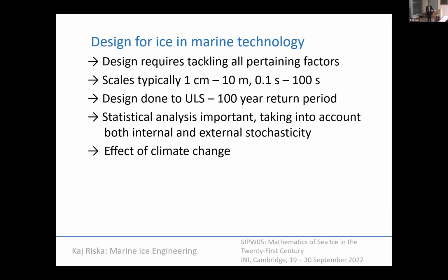Then there's an effect of climate change. That has been debated a lot. And actually the present opinion in engineering is that if your statistics proves that there is some sort of effect of making the conditions more benign, less severe, what you should do is disregard that. It's put in one of the standards also. But then you end up with questions of how you should disregard that. That leads to very awkward questions in doing design, and this is something that has to be taken into account.